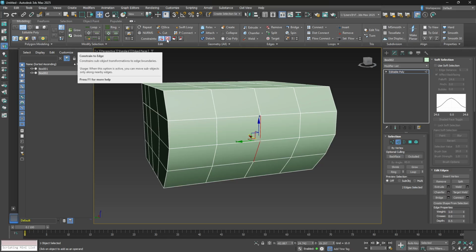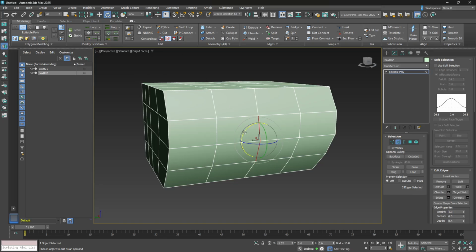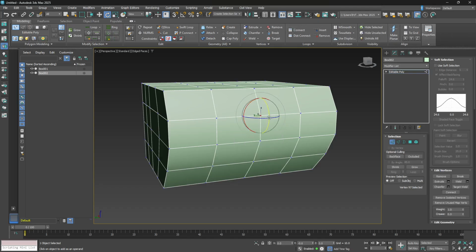Here in Max and in Maya, this is something you'd have to get used to using. You have what's called edge constraint, right? So we can now switch over to rotation. We can actually just rotate this right here, no problem. And it slides along the edges more or less. Edge constraint's kind of like GG twice, but it's a little bit better in some ways. And so you can see it will lock to the edges, doing as such like so.